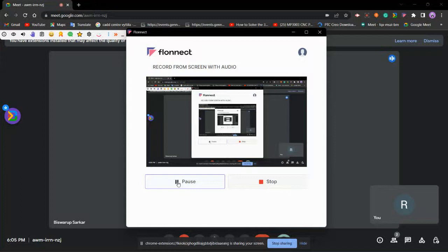Our sketch is this one. If I'm reversing it, the thickness is going inside our sketch. Only for this thin feature, the line can be closed or open, but otherwise it has to be fully closed.